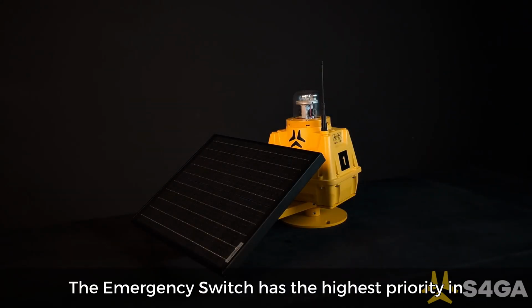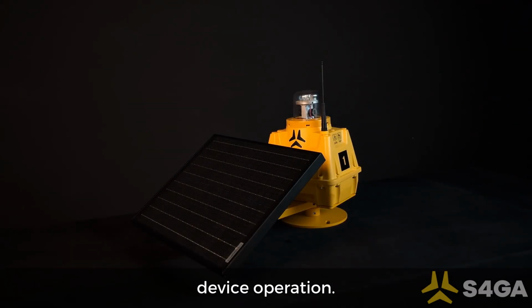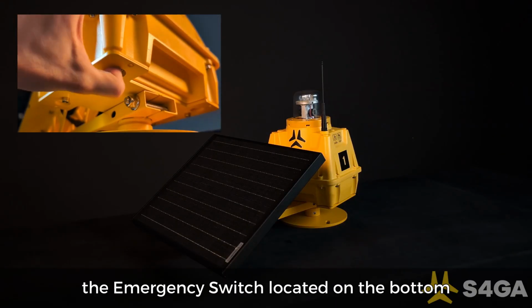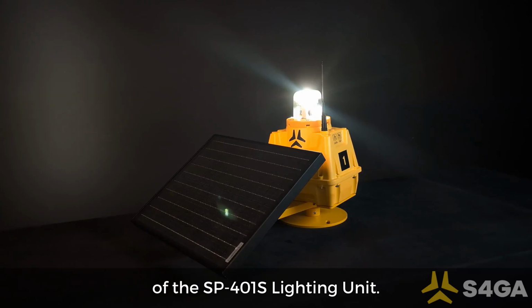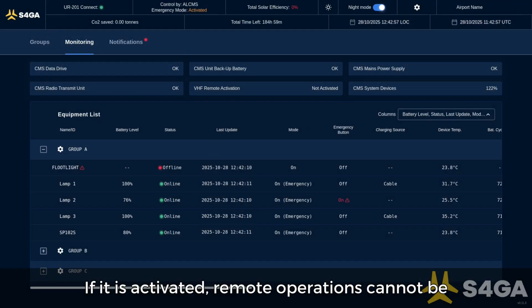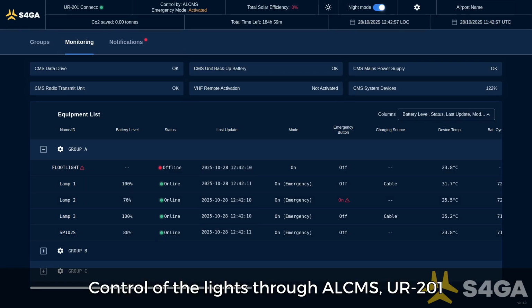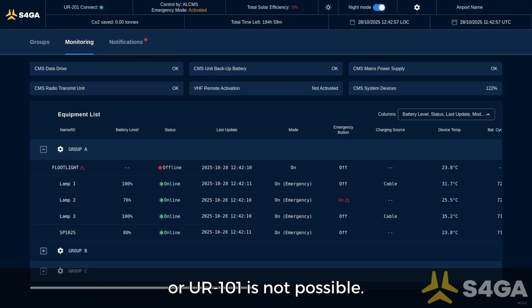The emergency switch has the highest priority in device operation. To activate emergency mode, press twice the emergency switch located on the bottom of the SP-401S lighting unit. If it is activated, remote operations cannot be performed. Control of the lights through ALCMS, UR201, or UR101 is not possible.